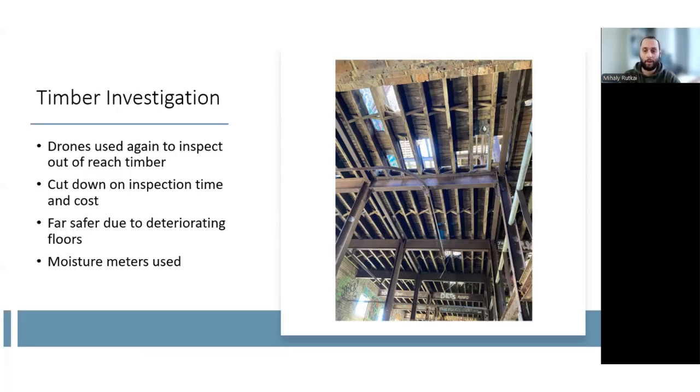With the rotten flooring, it was deemed very dangerous to actually access any of the upper floors. Without drones, erecting expensive and time-consuming scaffolding would have been our only option to inspect the structural timber elements at the upper levels. Instead, just a drone recording and scanning via LiDAR was able to get all the data that was needed to grade all the timber within the structure.